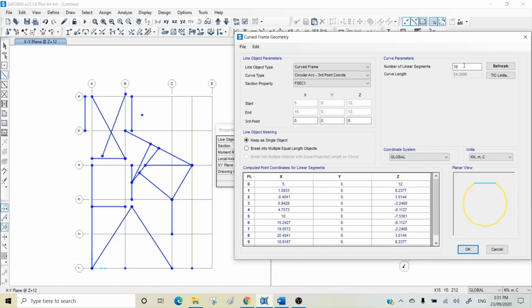Also, it shows you the number of segments at the corner, and you can change the number of segments to whatever you want, depending on the geometry you want to create. Roughly I know this is 6, and then we have a longer space, maybe 8 meters or something, and then 3 meters. So I think this is maybe 5 and 7. Roughly this area is around, say, 10. So if I choose 10 and 6, 10 for X and 6 for Y,